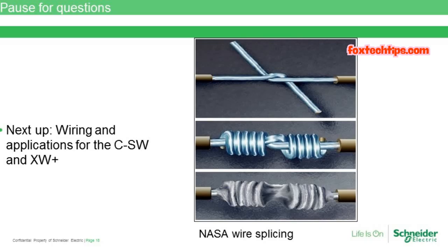One other thing to note with salt batteries, such as with Aquion batteries, I do understand that some of the technology has been evolving with Aquion, but something worth checking with the manufacturer is once the batteries have gotten to a lower discharge point and we have a low battery cutout, what's going to happen is that system's going to continue to discharge down. Whereas with AC coupling, of course, the low battery cutout for the inverter stops creating that AC signal, and so the grid tie inverter is not going to produce any AC.